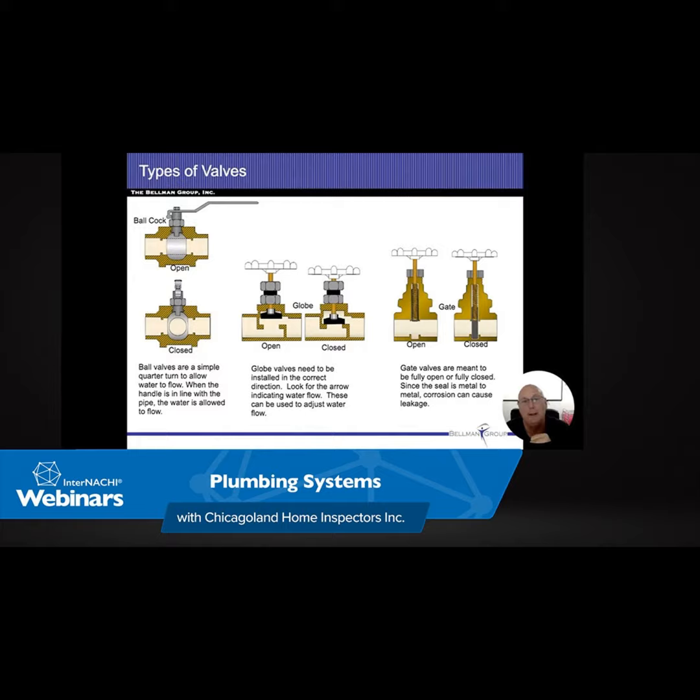Water heaters are typically going to have an ANSI code on them as well. So if we look underneath that star, the American Association, the NRTL design up there, when we look underneath there, we see 1998. So that's the code that this water heater was manufactured under, the code of 1998. Now, codes typically go for 3 or 4 years in that ballpark. So just by seeing that ANSI code, I know that this thing is going to be from 1998, 1999, year 2000, or the year 2001. Next thing I do is I look at the serial number.